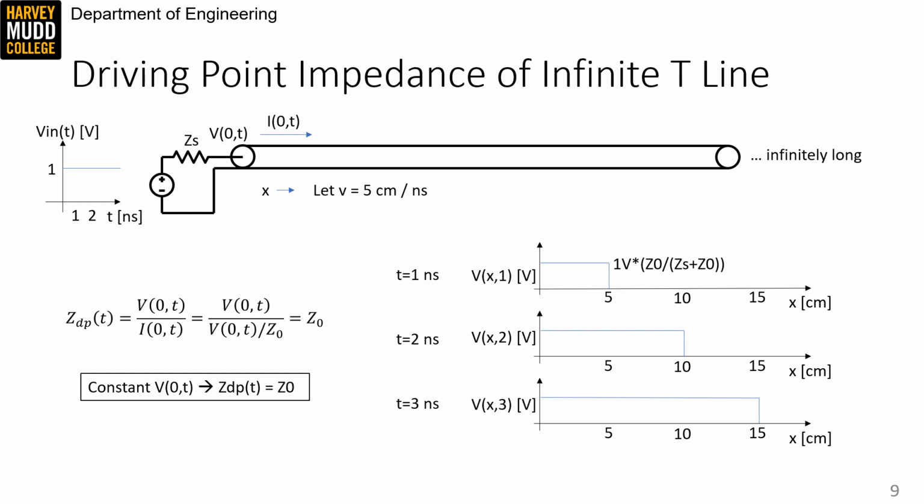Second, we might also notice that Zdp is a real impedance, which suggests that our power supply is dissipating real power in it. That's weird because this is a lossless transmission line made entirely out of lossless inductors and capacitors. However, we can resolve that paradox because, from the perspective of the power supply, it appears to be losing power down the transmission line. It throws power into it and it flies away, propagating down the line forever.